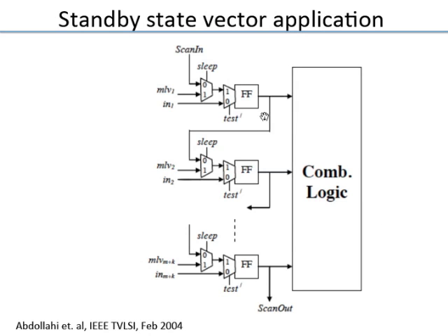Now, to put in those test vectors, because these flip-flops are all deep inside the chip, you have half a million flip-flops. You cannot have that many pins. How do you put in information and set a particular pattern? You do it in a serial way. All flip-flops are chained essentially, so one by one you shift it. It's a slow process, but you do it only during testing. Shift it in, let it settle, check the output, shift it out. Like that you keep doing.